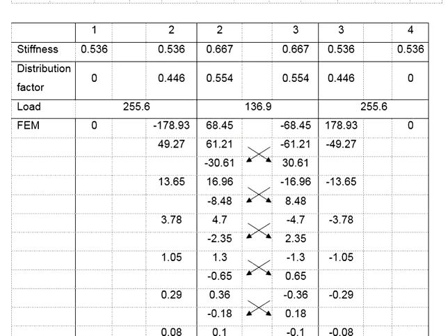Having the moment here, assuming this side will take half and the opposite side will take another half, you will carry forward half of the moment to the opposite side. Same process goes here. Half of it will be carried forward. As for this end, since we assume it is a pin connection, it is not going to take any moment. Therefore, you cannot carry forward any moment here. And since you have no moment to be carried forward here, you also do not have any moment here. That brings the balance moment here, and later it will be multiplied with the distribution factors to get the moment here, and multiplied with the distribution factors to get the moment here.